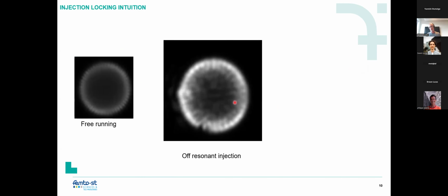So how do we process information with these devices? Here you see the laser without any optical input, just electrically biased above threshold. Now we inject a multimode field. This could, for example, be a scenery, an image, a pedestrian walking across the camera of a car, or it's not a camera, in this case the laser, but the pedestrian walking is injected into the laser. If we do off-resonant injection, you see nothing is happening. It's just two fields, the intensities are superimposed and squared, and there's no real interaction. I.e., we don't have a nonlinear transformation, we do not really have a reservoir.